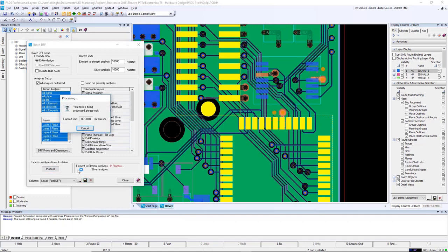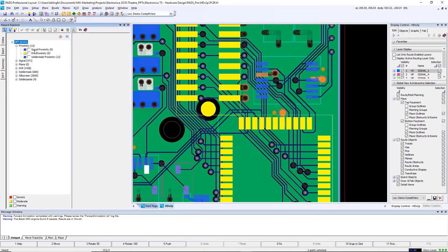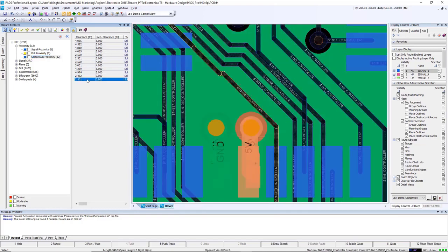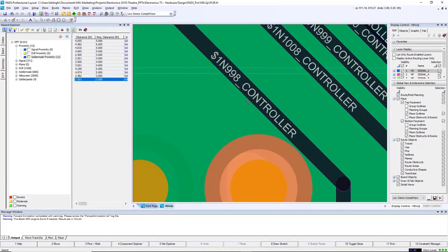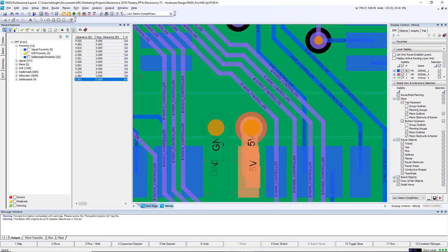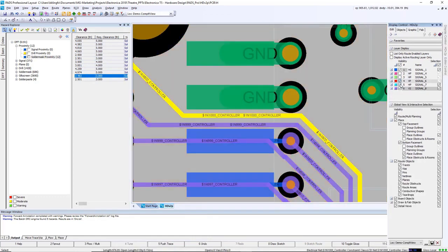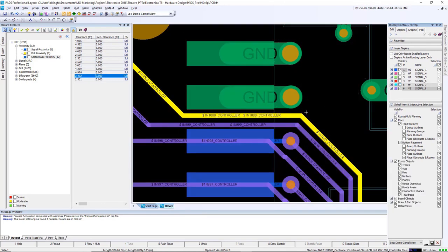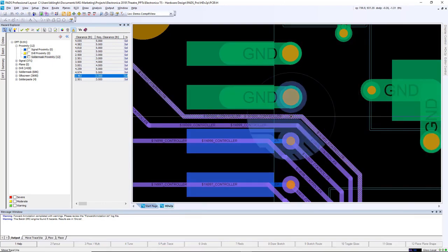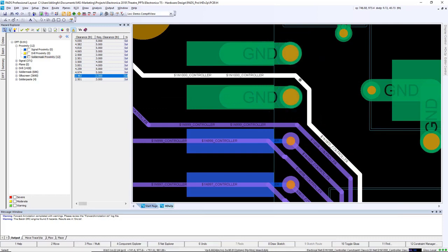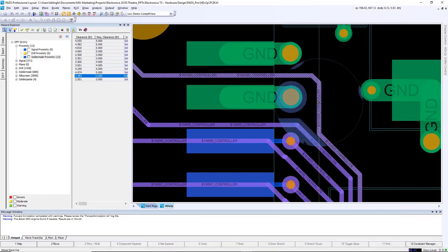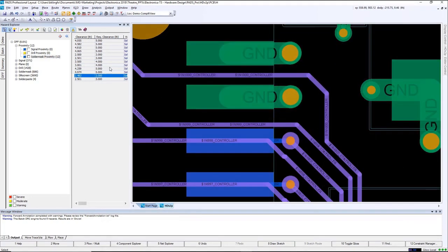Once the rules have run, you can go to your Hazard Explorer. There'll now be a DFF tab available. There you can see each category and if there's violations or not. In this case, we'll look at a couple of solder mask proximity violations. You can navigate to them by simply clicking on them in the Hazard Explorer. It'll take you to that violation in the design. Once found, you can use the push and shove technology in PADS Professional to simply fix the issue. Not performing this level of verification can lead to fabrication delays, assembly delays, and possibly quality issues down the road.